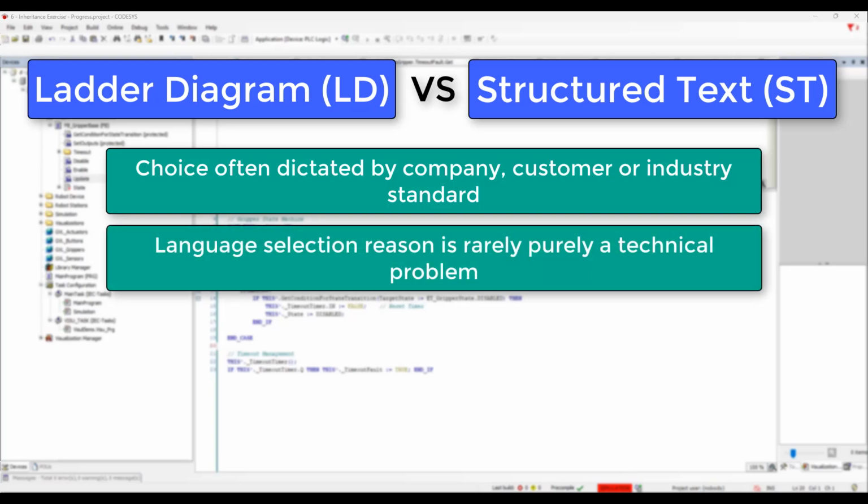If you work for a process end user, where the priority is maximizing uptime and troubleshooting is done by maintenance technicians working multiple shifts across different lines, you will likely use a ladder diagram. And if you work in an R&D department of an OEM building standard complex machinery and you need to support a massive install base with efficient updates, you will likely work with structured text.